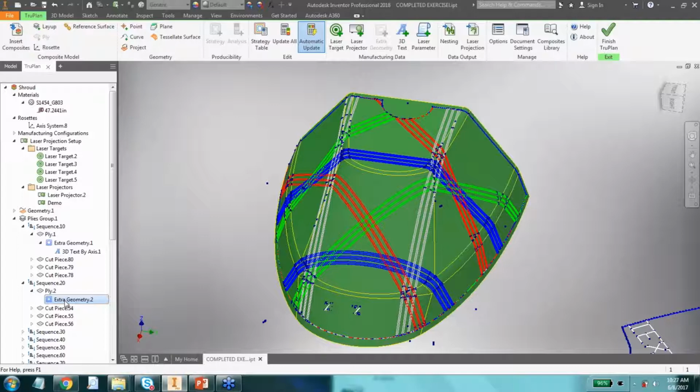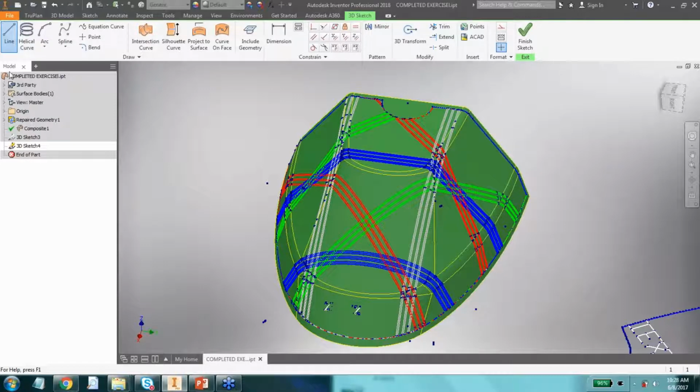And the first thing I would just want to talk about is if you wanted to include extra geometrical information. For example, a simple line segment. So what I'll do is I will say I want to create a curve, and I'm going to just move over to my existing sketch and say finish.